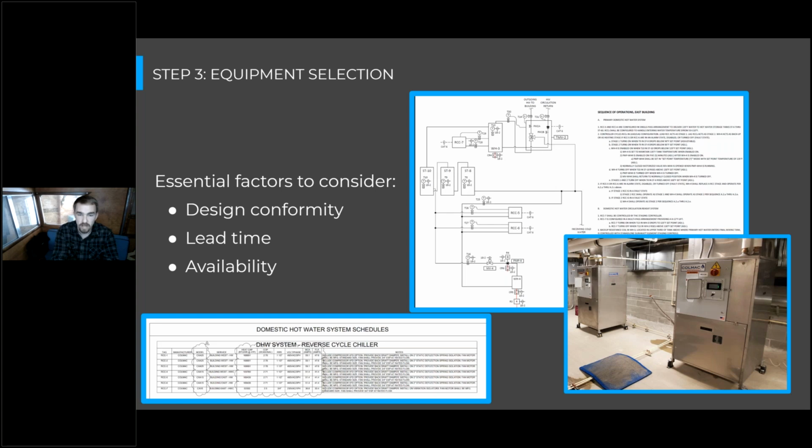We mentioned Colmac in the Jackson Apartments case study, having a minimum air temperature allowance of 40 degrees. So if this design had the heat pumps located on the roof, or there wasn't this garage buffer, then you wouldn't be able to just drop Colmacs in and have them operate successfully, right? So if they specified a heat pump that was meant for that cold air, you want to make sure that this new heat pump you're proposing will fit with that cold air and that piping configuration.